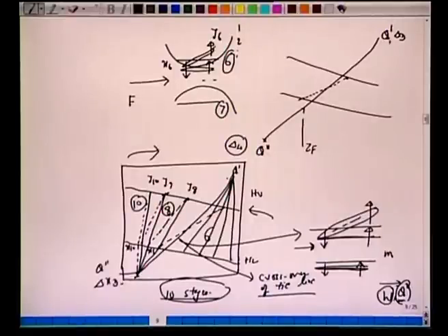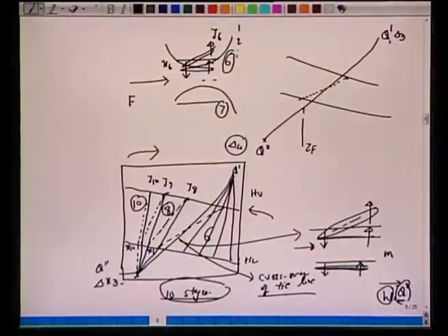All right. So in this example, what we have done today, we have addressed the complete distillation column, including the condenser and the boiler. In the condenser, it was a total condenser, so we didn't have any theoretical stage for the top. For the bottom, it is always a boiler, always a theoretical stage. So here also the last tie line which will cross this XW will also represent the theoretical stage for the reboiler. So let's complete our discussion with the last stage here.